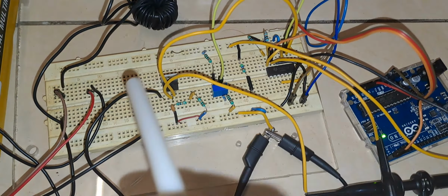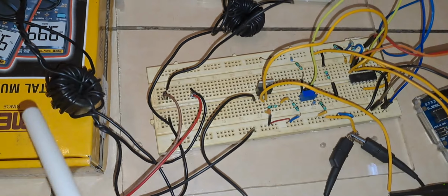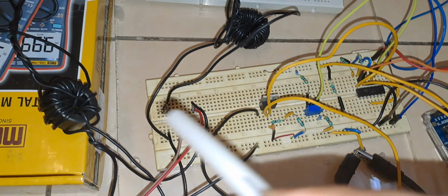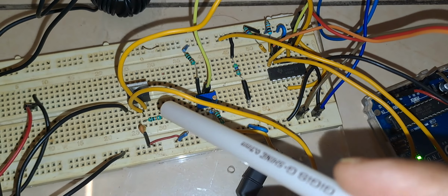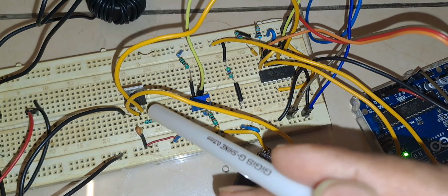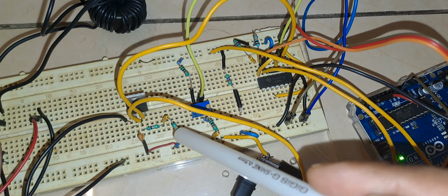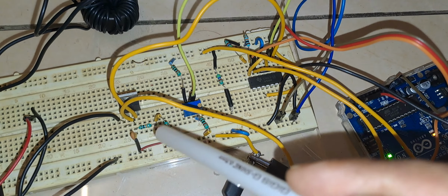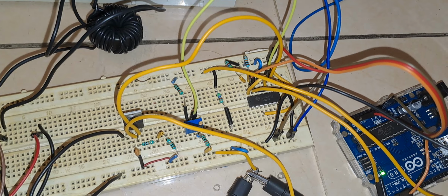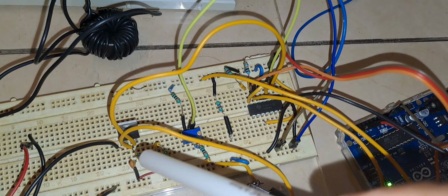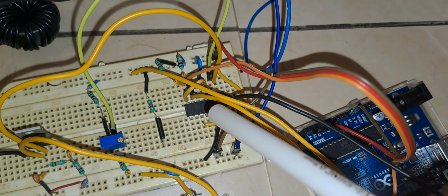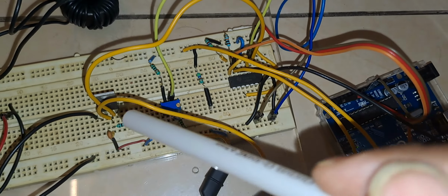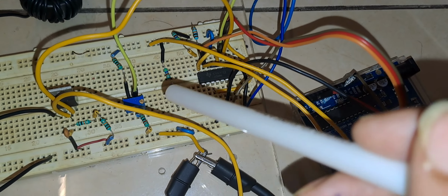So now here you can see this is the receiver unit. Once the data is received by the receiver coupling transformer, it is fed to this demodulator. You can see this is a Schottky rectifier. Here is a capacitor and here there are two resistances. So this is a demodulator. The output of this demodulator is fed to this comparator. This comparator compares the output of the demodulator with the reference voltage.